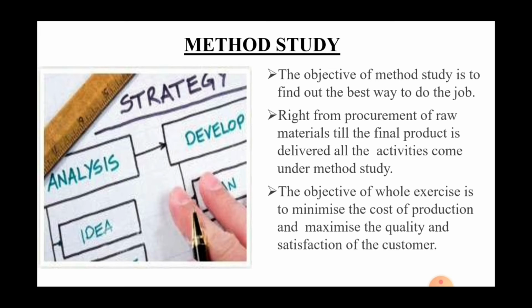This is generally achieved by eliminating unnecessary motions involved in a certain procedure or by changing the sequence of operations or the process itself. It provides efficient and faster material handling. It provides better quality. It reduces fatigue to workers. So method study basically simplifies the overall methods which are used for a production process and helps to reduce the cost of production.